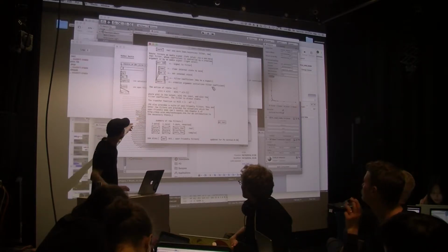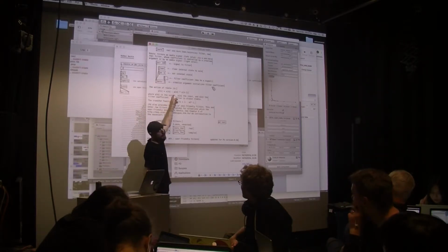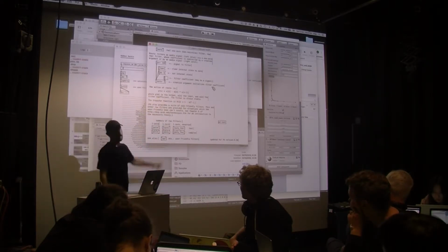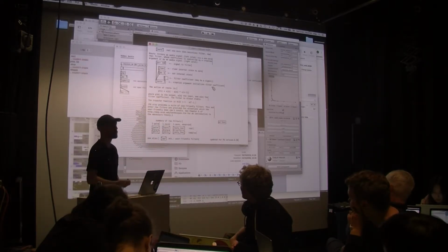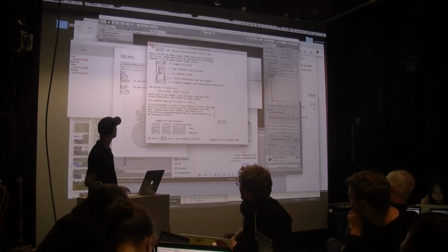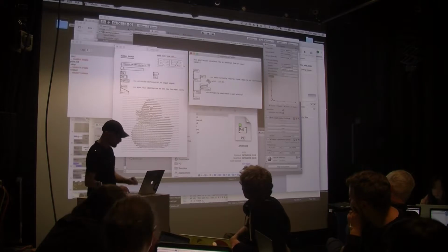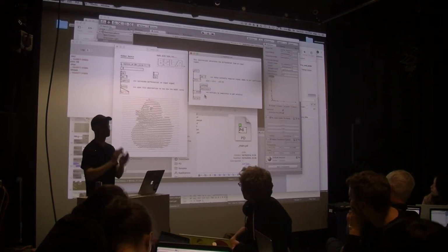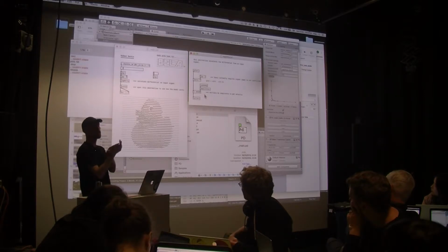So what that means is if A is set to 1, then what we're going to get is the difference between x of n and x of n minus 1, okay? So if you use rzero~ 1, you've basically got a very simple audio signal differentiator. You calculate the differential. Obviously, you have to take the sample rate into account because you've got to divide by the time step, which is the time it takes for one single sample to occur.